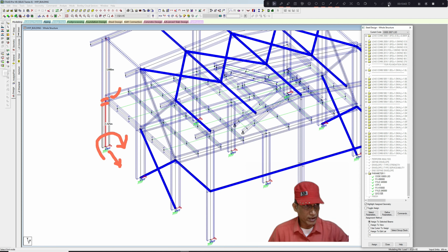So let us clear the drawing. We have this one, press Ctrl and select this one. This has a tube which shall be provided end plate. So we will provide torsional resistance here. Then this one also, so select that.